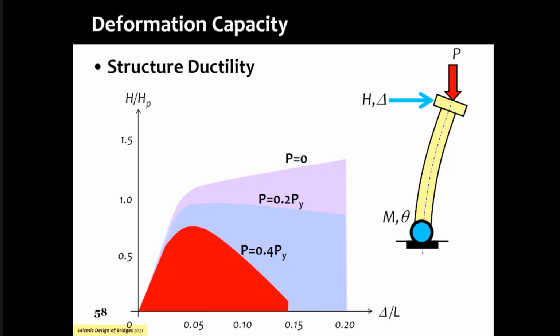If you choose a silly size column, a very small slender column, the ratio of the applied axial load to the maximum capacity, if that ratio is very large, close to 1, you are in trouble. In your PM interaction diagram, if you're in the top apex of the PM interaction diagram, you're in trouble. So the thumb rule again is healthy column sizes. No slender column sizes, but healthy column sizes will give you good structure ductility.